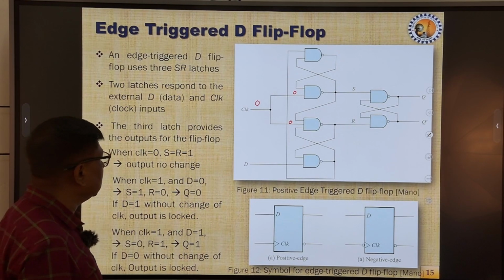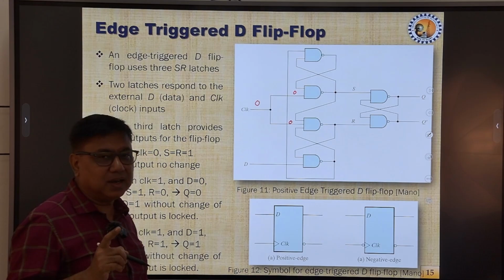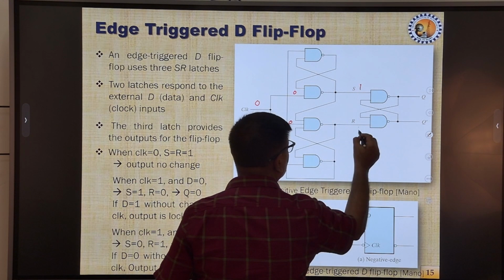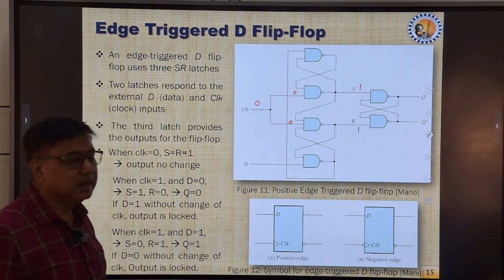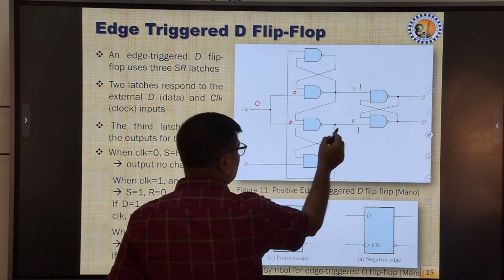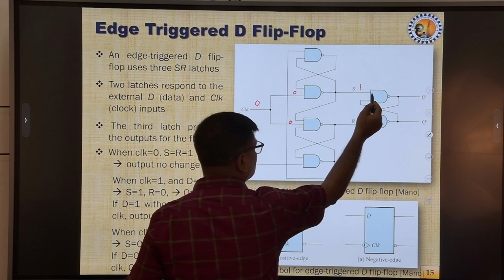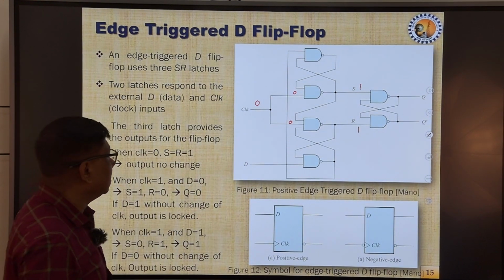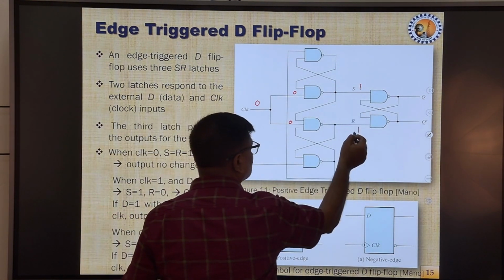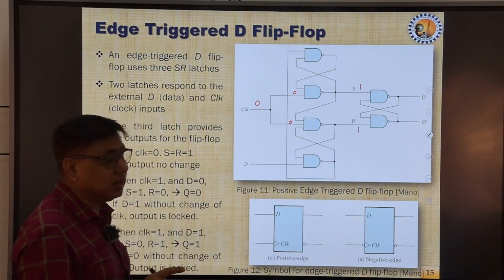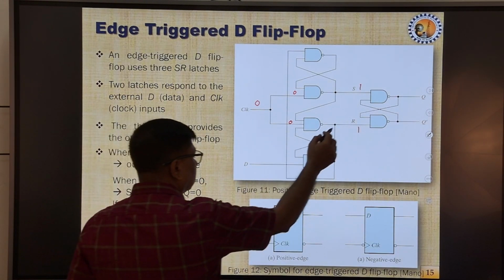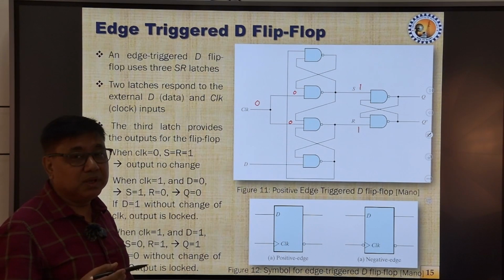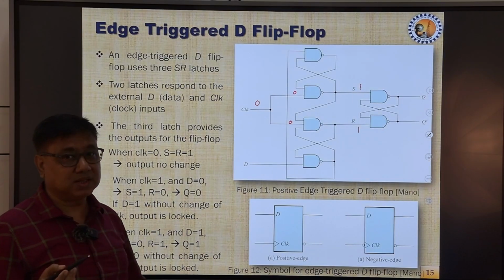We know that for a NAND gate, if one of the inputs is 0, its output will be 1. So the output of both the NAND gates is 1, and these are connected to the inputs of the output NAND latch. So over here these inputs also receive 1 and 1, and 1 at the S and R inputs of the NAND latch makes the flip flop hold its previous state.